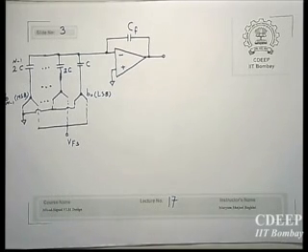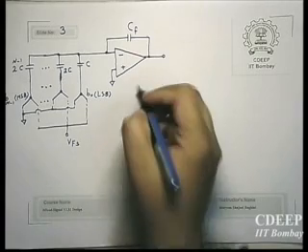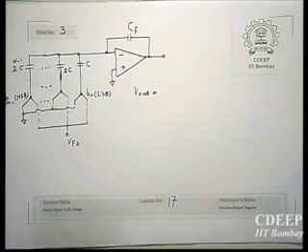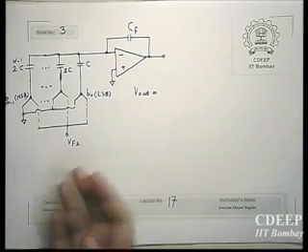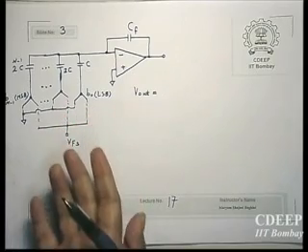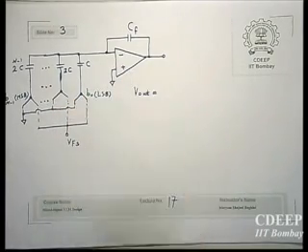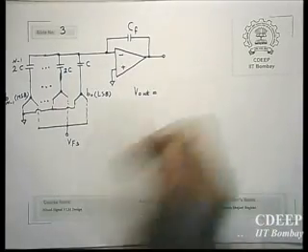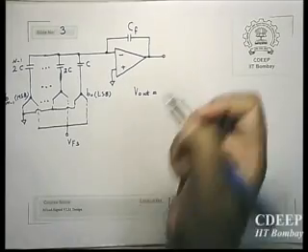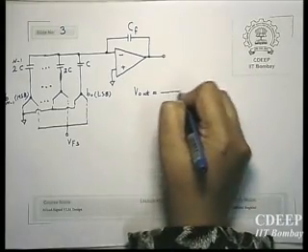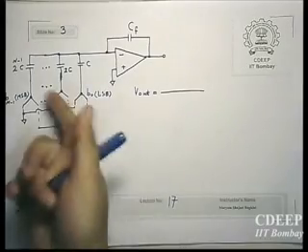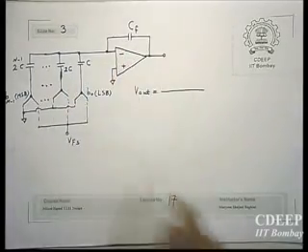So now it's the same as before. So output voltage. Eventually what happens is that according to your connection to V full scale and ground, you will get some charge on these capacitors which will be eventually shifted to CF, and therefore this is like an inverting amplifier. So the same relation is valid. The charge stored on these capacitors is a function of input code, and this total charge will also be transferred to CF.